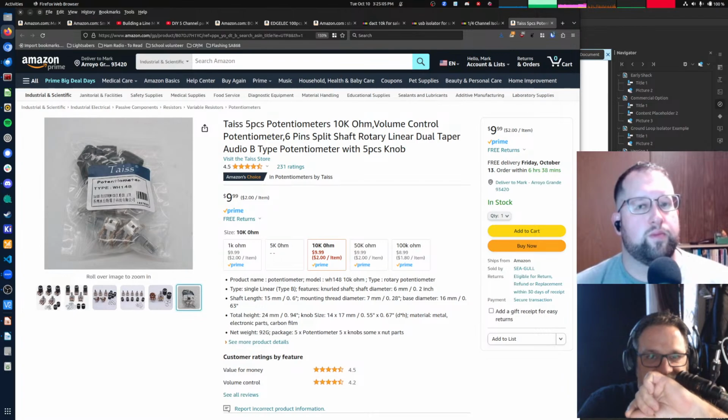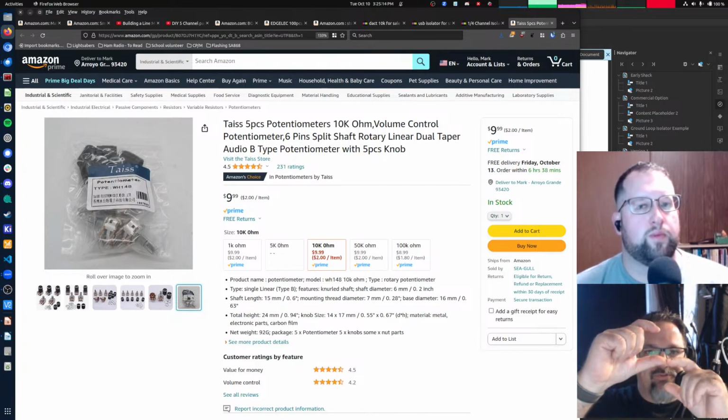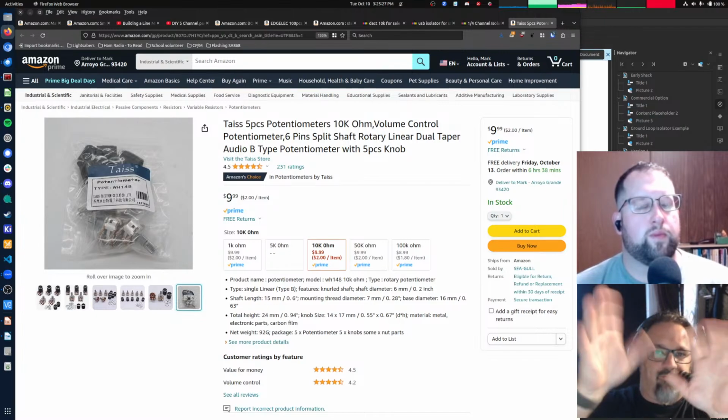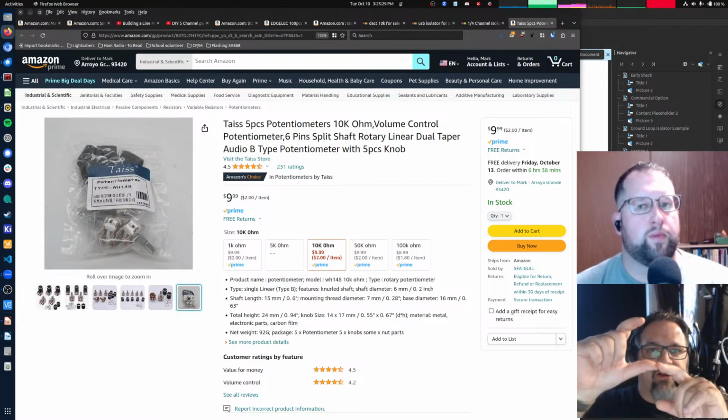If you take that knob and put it right smack dab in the middle, halfway between fully clockwise and fully counterclockwise, and then measure between the wiper and the top and the wiper and the bottom, if it's a 10K pot, you should get roughly 1K on the bottom and 9K on the top. Hand-wavy numbers, the numbers are not exact. Instead of 5K and 5K, you should get 1K and 9K.